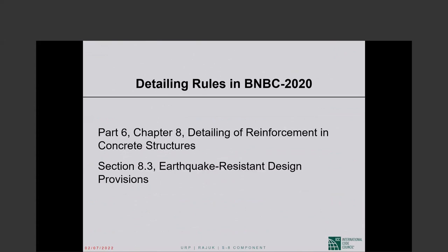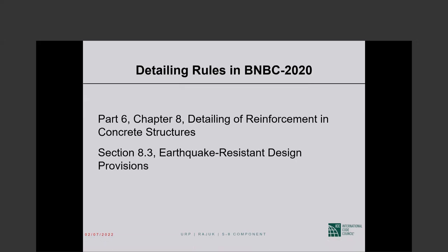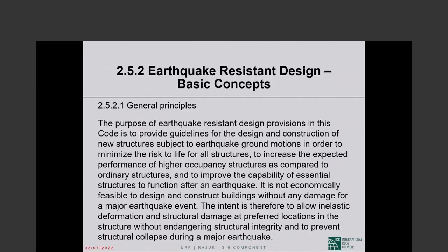And then part 6, chapter 8 has the detailing requirements, detailing of reinforcement in concrete structures. That is for all concrete structures. If you want earthquake-resistant detailing requirements, those are in section 8.3. So we will make use of them, not today, but starting on Wednesday.